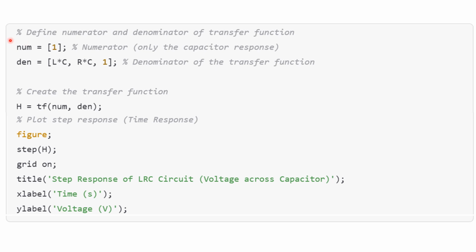So this is a very simple MATLAB script that you should run that sets up the transfer function that we just saw. This creates the transfer function, and this plots a step response to the transfer function. So again, you should plot this out and verify that you understand how to use MATLAB to generate the transfer function and get a plot out.